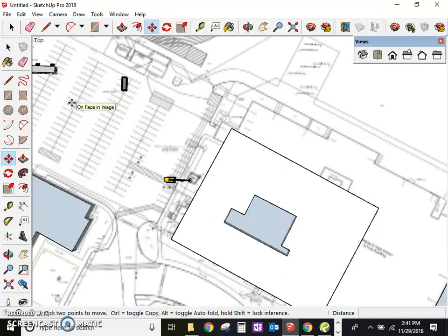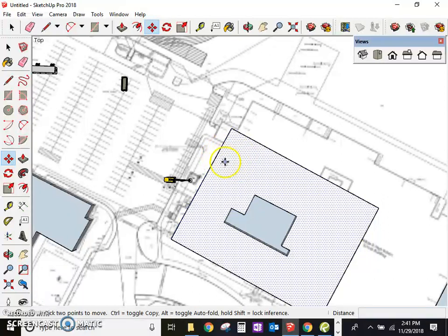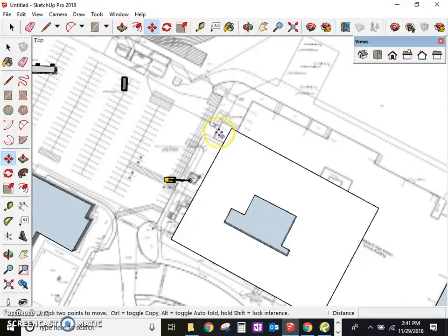Load your fence. So what we're going to look for is your crane's going to probably be set up in this location here on the parking lot. You're going to have to fence in that area so that people aren't walking underneath it. There's that loading dock in this location that you still want to have access to, or you need to still have access to. The loading dock's right there.